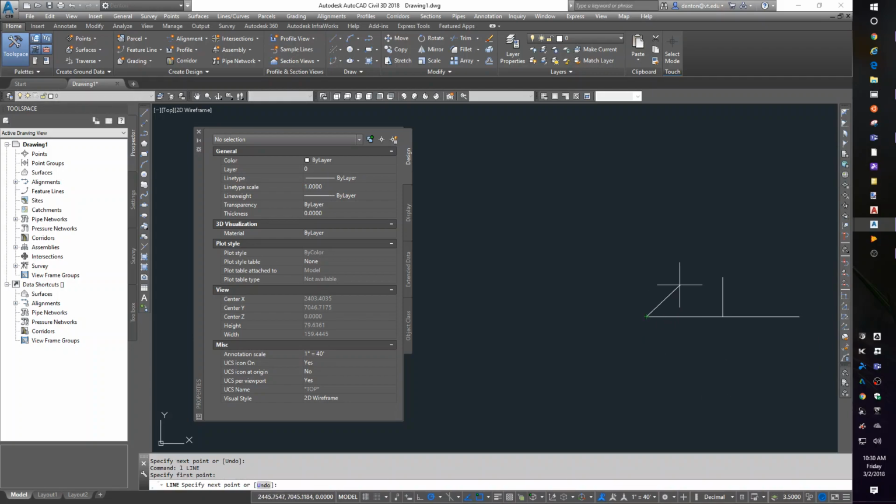Well, I can draw a line and say at some arbitrary distance, angle 20, and what that did was draw a line on 20 degrees, and if I use fillet with a 0 radius as a corner cleanup, I now know the distance, DI for distance, to the top is 6.3695. I have the height of that stockpile.